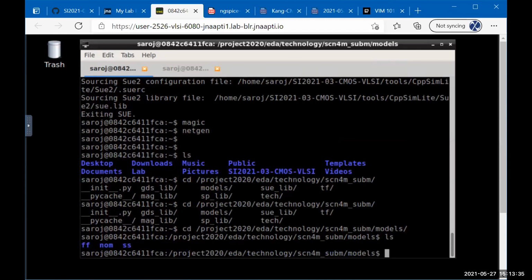NOM is typically what you would get out from the lab. Like we were saying, the mu n you're calculating will actually vary, and the variation is from process to process. The LD which you're putting in the model, the junction leakage into the gate, that also will vary from process to process. When I say process to process, every time a wafer comes out, it's going to be within those bounds. It's not going to be exact. So that's why they give you different models to make sure your spec meets for all the corners, all the limits.